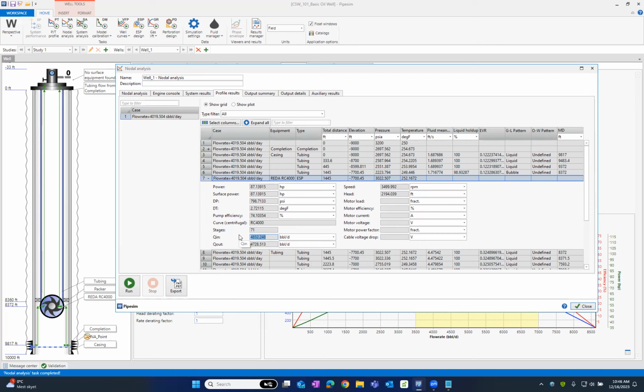Because of the formation volume factor. Or in other words, due to compressibility. When I have more pressure, what will happen to the oil? It will be compressed, right? So its volume will decrease a little bit, because now there is 800 psi added to the oil.